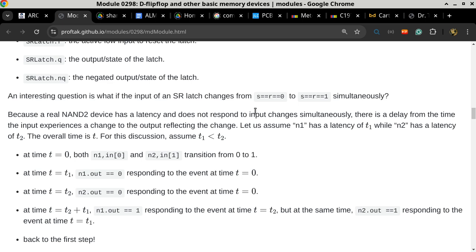And when you observe Logisim detecting that it is in an oscillation, you don't understand either, because the mechanism of why the circuit entered an oscillation state instead of a steady state can only be explained when you go through this process and see that, through these propagational changes, we went back to an earlier state, which means it's going to repeat this whole cycle over and over again. Does that kind of make sense?